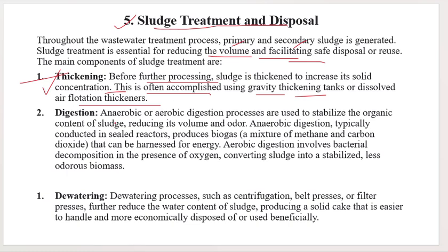Then digestion, anaerobic or aerobic. Anaerobic means in the absence of oxygen. Aerobic means in the presence of oxygen. Anaerobic or aerobic digestion processes are used to stabilize the organic content of sludge, reducing its volume and odor. Odor means smell. Anaerobic digestion is typically conducted in a sealed reactor.